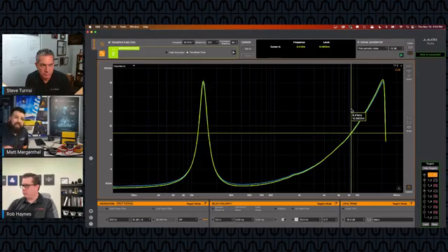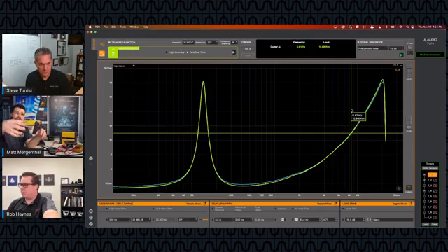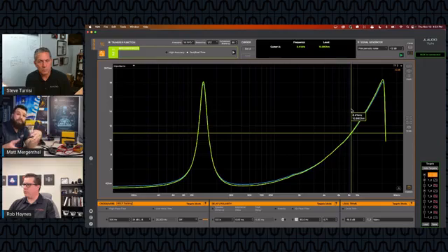And there are two other methods of the 4-wire impedance measurement, but in order to do those, you would need it basically doesn't use the TRS probe that's connected to max. What happens is it measures the voltage and the current externally. So right now we're measuring the voltage through the external voltage sense cable, and then the current is being measured through the TRS cable. But in the other applications, you could either use a current probe, which goes over the speaker wires and actually measures the current as it passes through those wires, or you could use a shunt resistor, which allows you to measure voltage drop across that resistor, but that would be in line with the measured data.